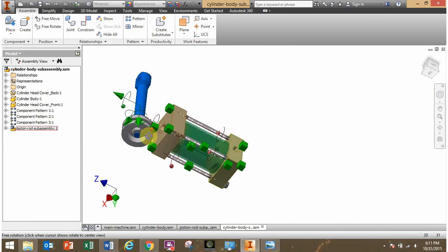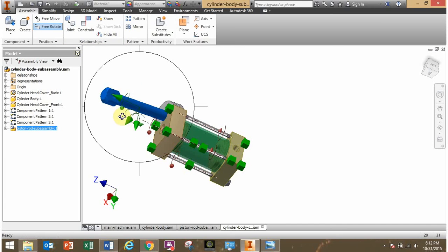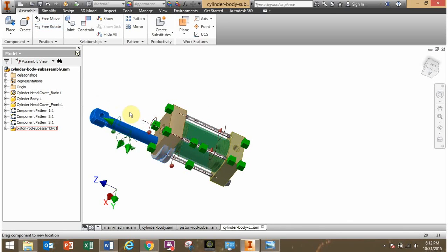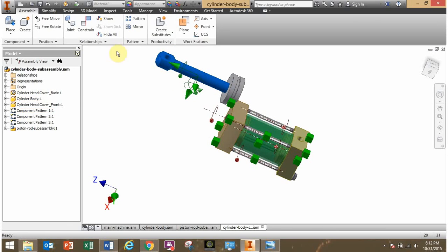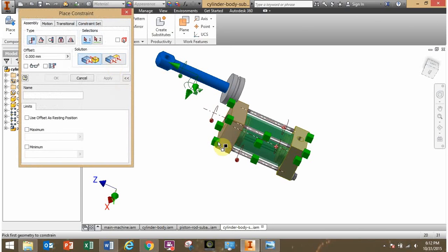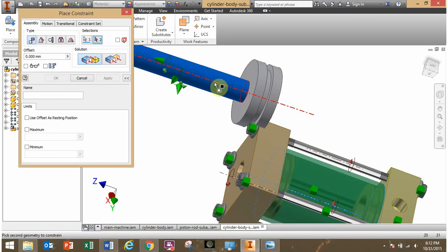All right, again, I'm going to rotate this to the proximate position. So click that and let's rotate it. It'll fit in about like this. Okay, hit escape. All right, let's start constraining this. Our typical procedure, I'll constrain the center axis with the center axis here. Now notice it doesn't matter if I do this center axis or this one, they're all the same axis here.